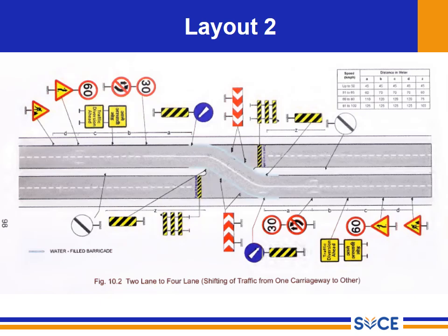The camber here is towards the drainage. Here also towards the drainage. If you see the camber, here it is totally changing direction. That's why I'm saying both are in opposite directions. So that should be properly merged.